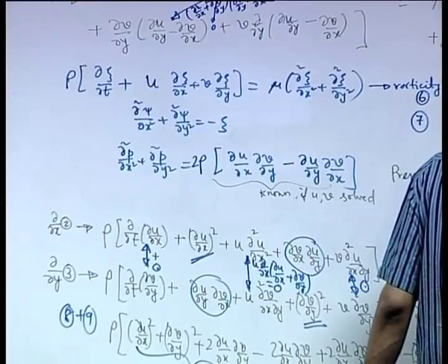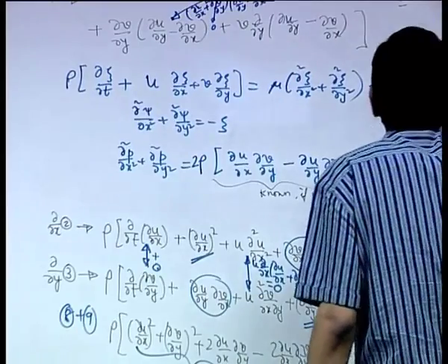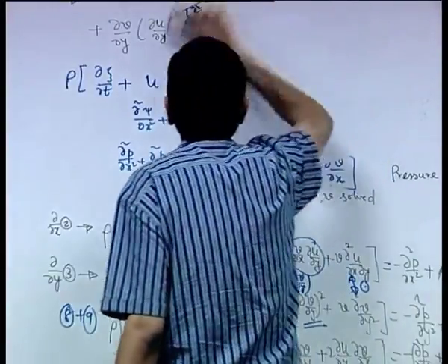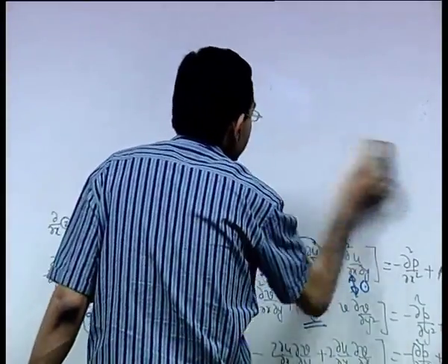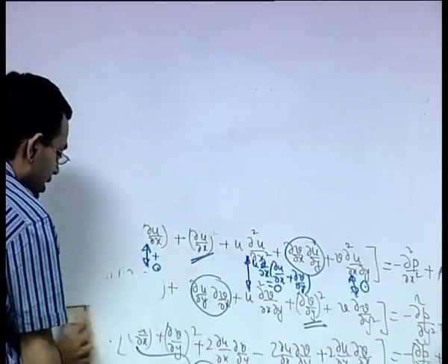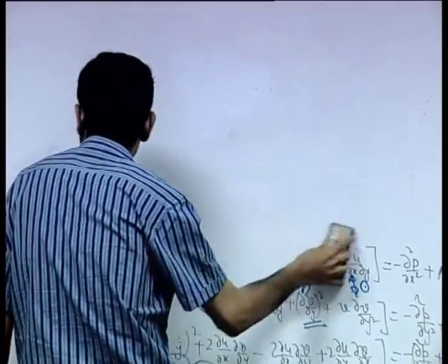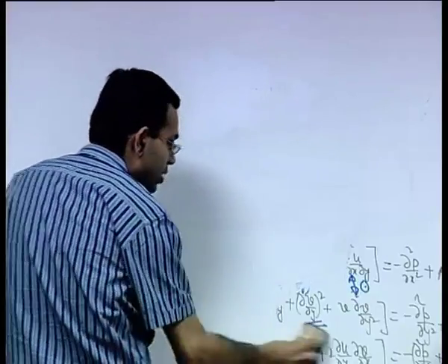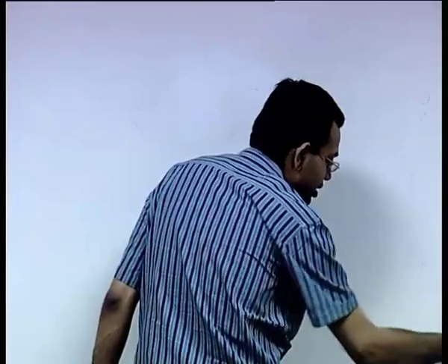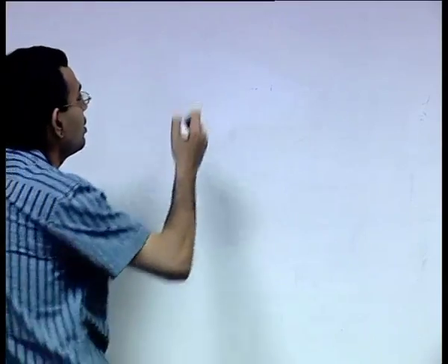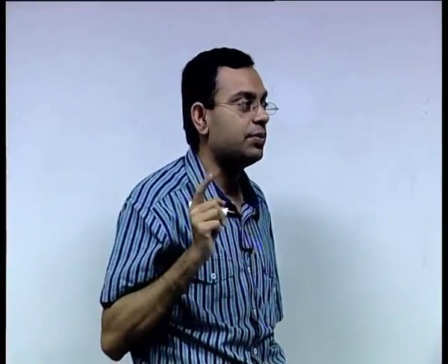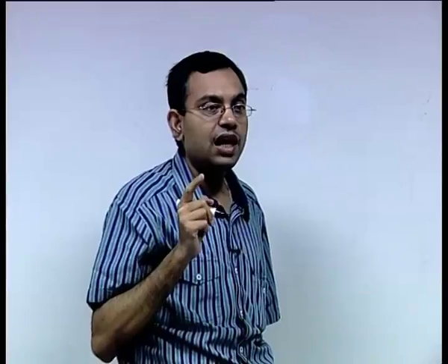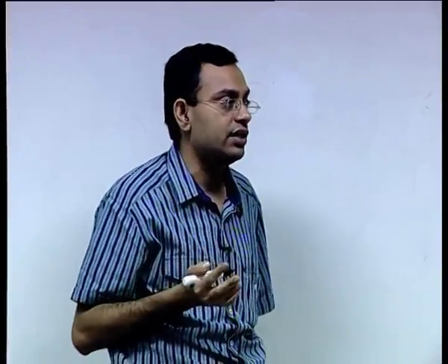If we are interested in the primitive variable approach, there are certain restrictions or obstacles that we have to face. One of the important obstacles is the calculation of the pressure gradient term. The pressure gradient term, if you recall, acts as a source term in the momentum equations. So, let us see how we can approach that. Our objective is not to eliminate the pressure gradient term, but to retain it and see what challenges we face if we retain it.